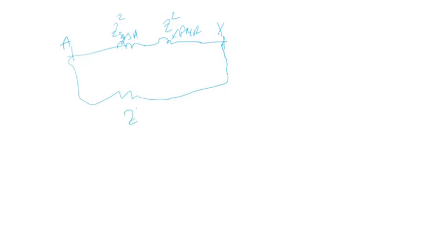So now let's draw. The negative sequence impedance will be kind of similar. You have the negative sequence of system A, then you have the negative sequence of the transformer, which is the same as the positive sequence. So you have X, then system B is in parallel. And this is the negative sequence current that flows through the high voltage.